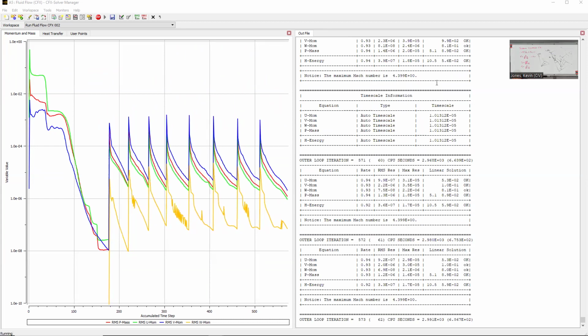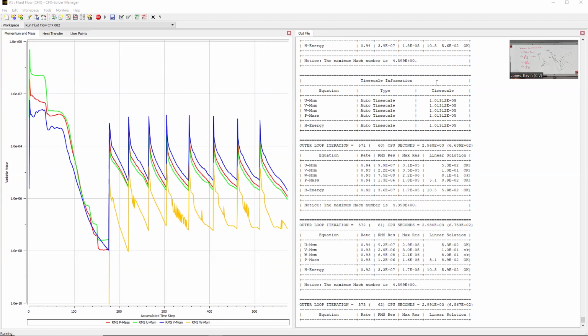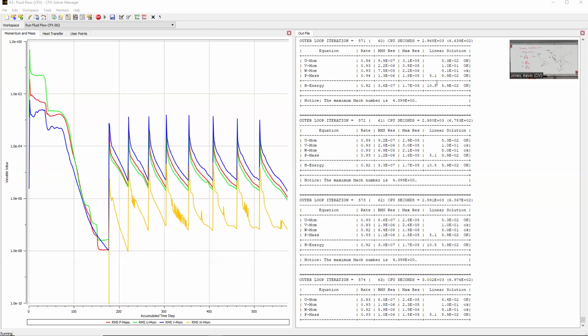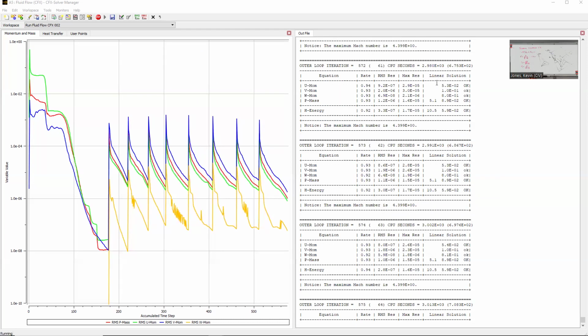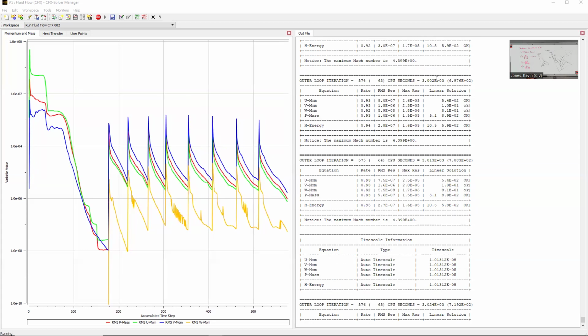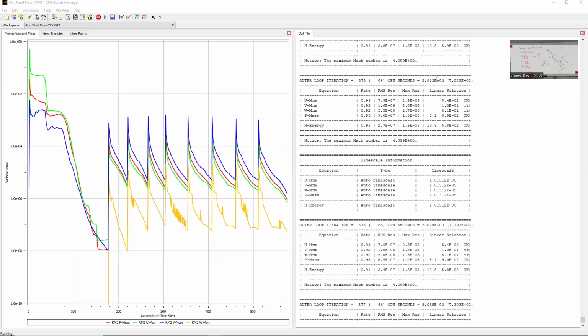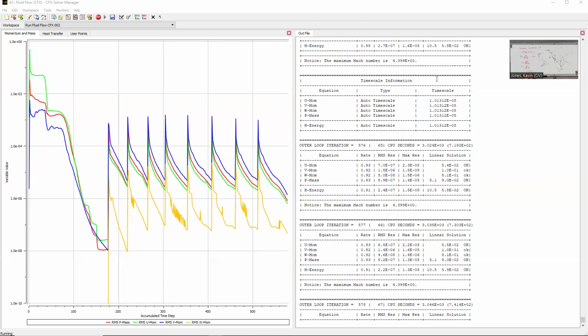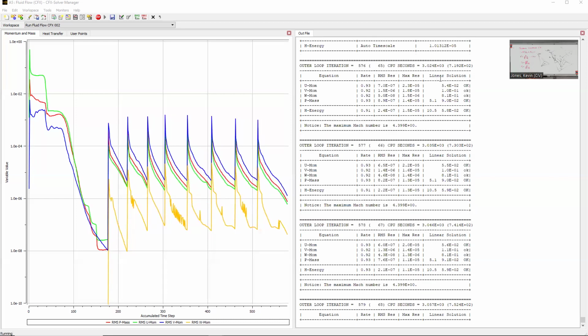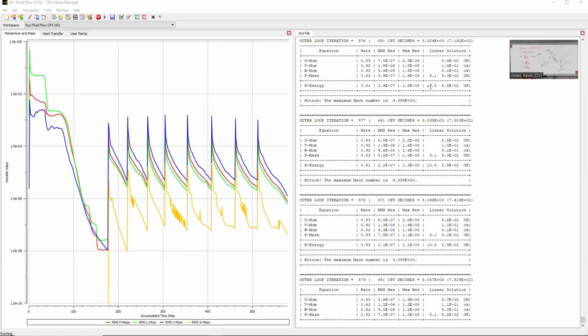It's some variation going on in there, I guess. I never looked at it. They quit using Navier-Stokes, so it becomes kind of another area of aerodynamics for rarefied flows. So if you're into reentry vehicles, you quit using Navier-Stokes and you start using Monte Carlo methods. So you literally treat molecules as individual particles, and do probability studies of particle impacts.